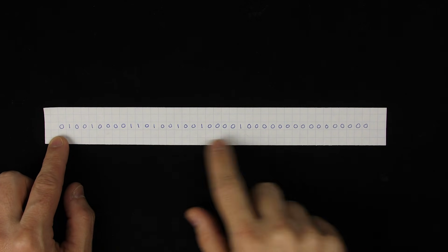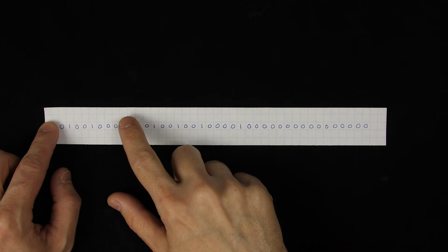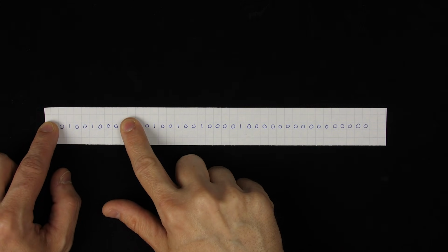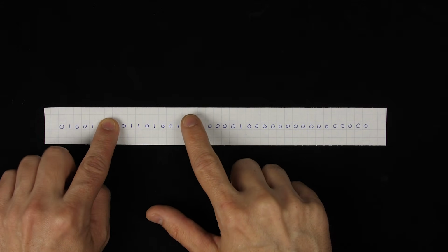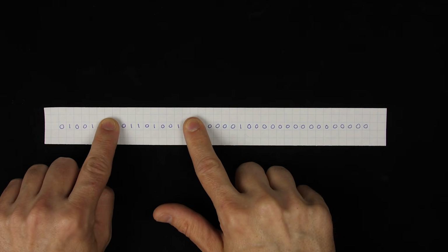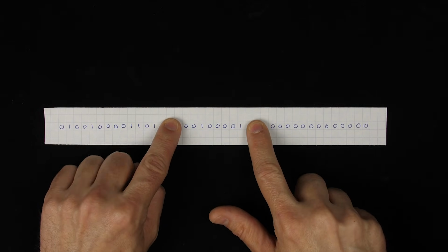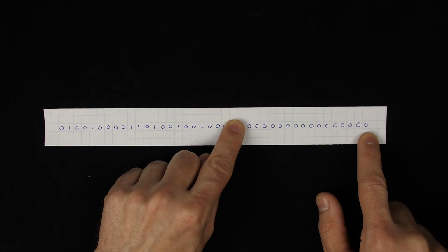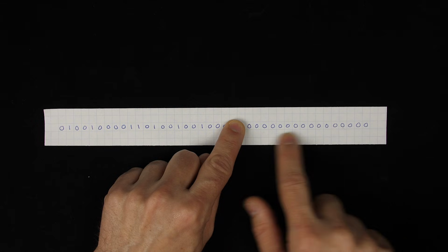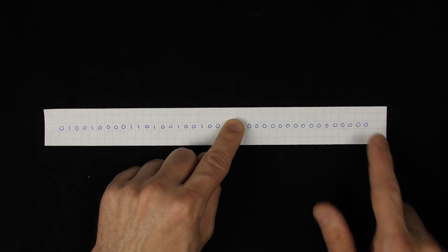So it all starts with the message that we want to send. If we chunk this up into little 8-bit chunks, we've got an H there. That's the ASCII for an H, or the binary representation of the ASCII value for an H. That's an I. And then here we have an exclamation point. So it's "Hi!" is our message, followed by 16 zeros. And these 16 zeros is where we're going to put our 16-bit CRC.